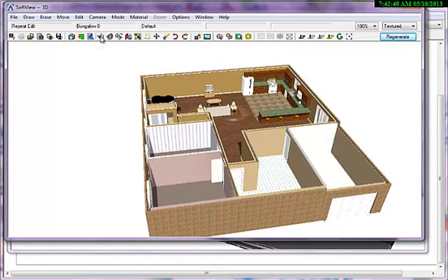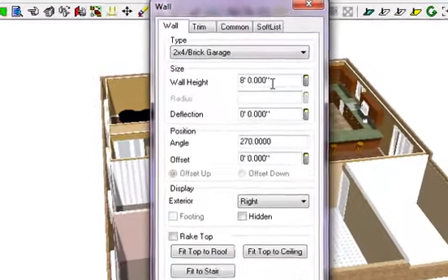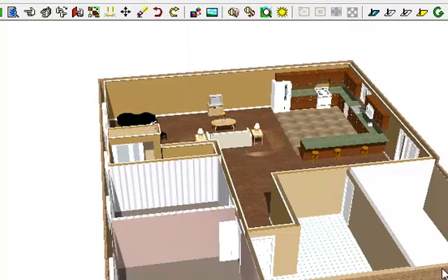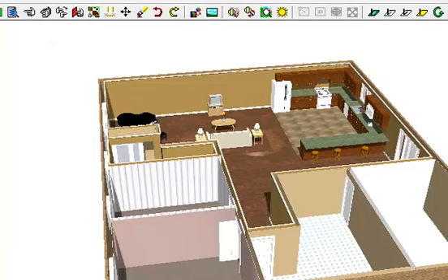I'm going to do this in the solid build. I'm going to click on the wall, and I want to keep the offset at 0 on these walls. I still want them down at the bottom. Now I've got to make this 8 feet 11.625. It's a good thing to remember: it's 11.625 inches that the floor system adds. So I'm going to say OK, and now this is level along the top. I'm going to do a repeat edit on the other wall, and now I've got it all set up.